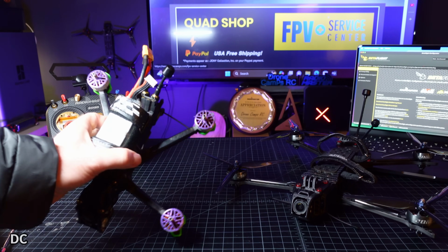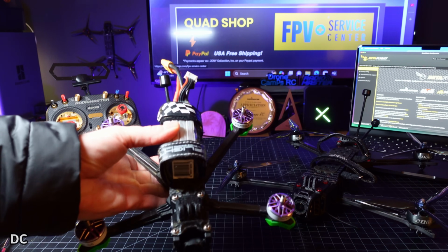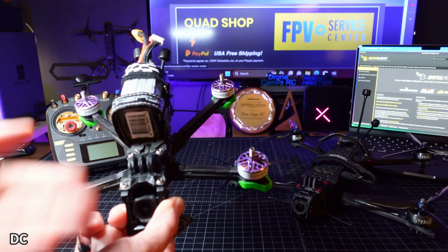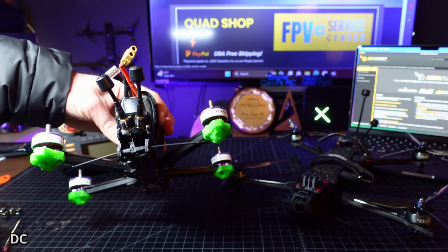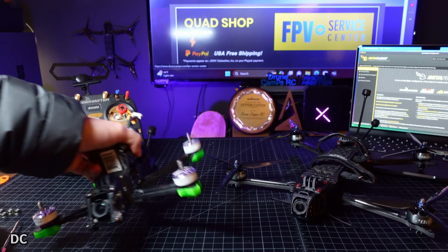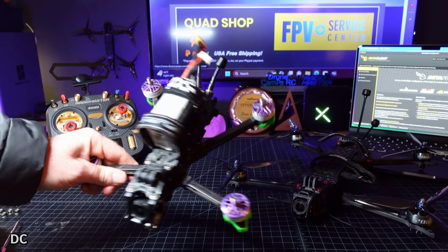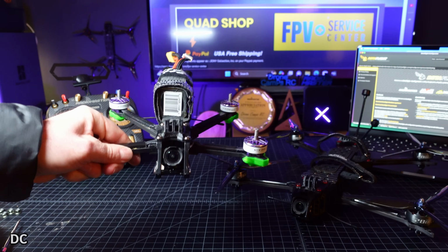But this placement is not very optimal because sometimes when you're flying back toward yourself, you can see that this antenna is kind of blocked from the front. And when you're flying away from yourself, the rear is totally exposed line of sight wise. You have a perfect connection to this antenna back from your radio. When you turn around and come back the other way, you do have some blockage on a lot of different angles, almost complete blockage when I come down to level.